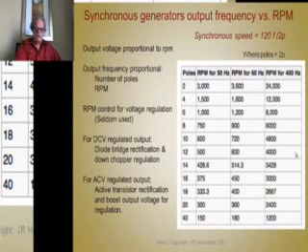So if you want 400 hertz out of the generator, which is what you want on aircraft, they have 400 cycle AC. If you want 400 hertz AC with no converter to rectify and regenerate the AC, then depending on the number of poles, that's the speed you've got to run it at to get that frequency.